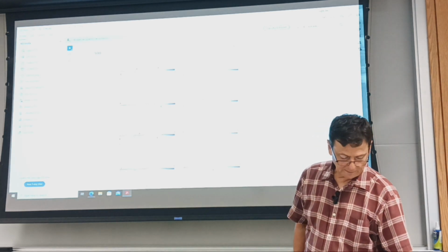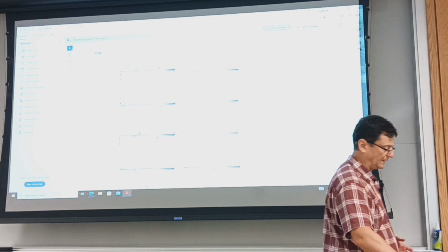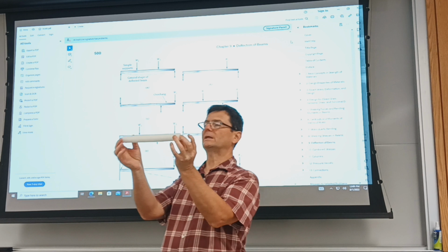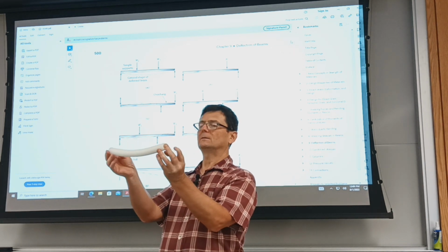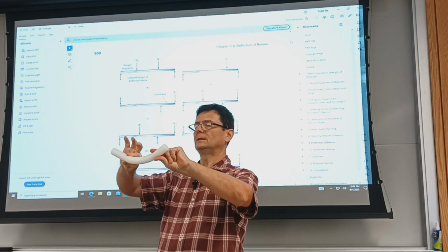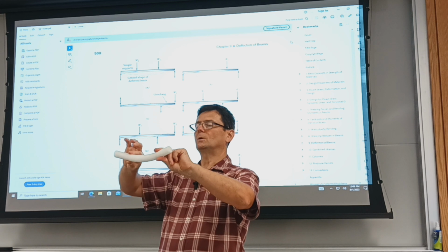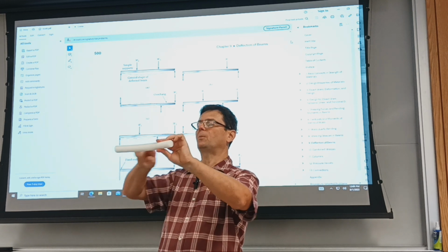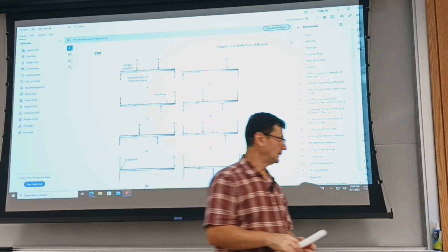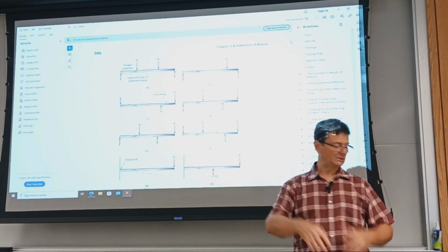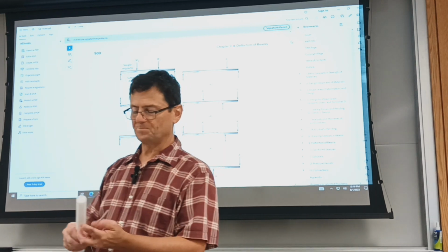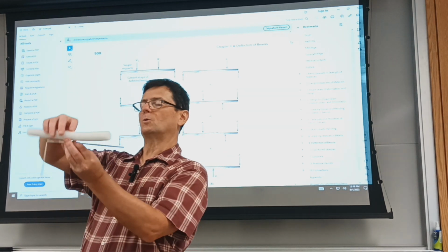So the study of deflection, that will be again just from an unloaded, perfectly straight configuration under the effect of load, and what I'm doing now, I'm applying 2 end moments. So one is how far points on a beam moved from the original straight line position, and then you also care, in consideration of the gears meshing, about the change of slope. That is, slope is the angle made with the horizontal of the tangent.